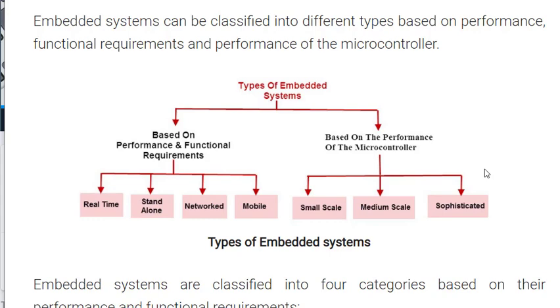Now for the standalone embedded systems, they do not require a host system like a computer. It works by itself and it takes the input from the input ports, either analog or digital, and processes. It also calculates and converts the data and gives the resulting data through a connected device which either controls, drives, and displays the connected devices. Examples for the standalone embedded systems are MP3 players, digital cameras, video game consoles, microwave ovens, and temperature measurement systems.